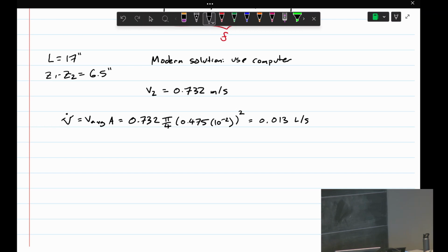Okay, so I need maybe everyone around here to time this. I'll tell you when to start your timer, and then stop your timer when it hits the 500 milliliter mark. So we're going to just do volume over time to get the volumetric flow rate. And the bigger the volume you use, the less error you get. There's going to be a lot of sources of error here. Okay, you guys ready? 3, 2, 1, go. I'm trying to hold this so that I get negligible entrance losses.